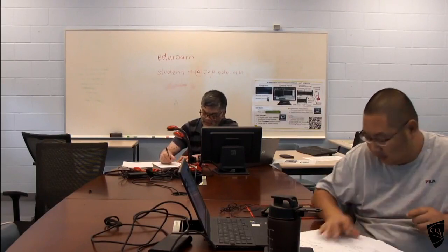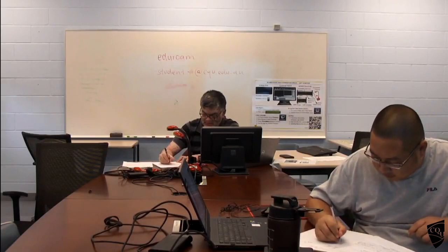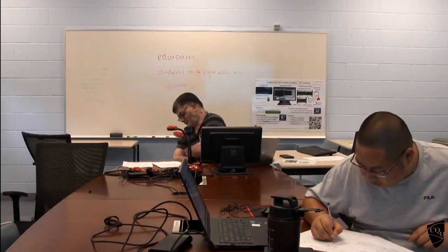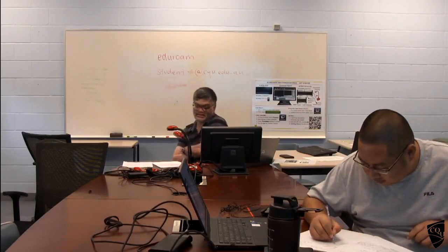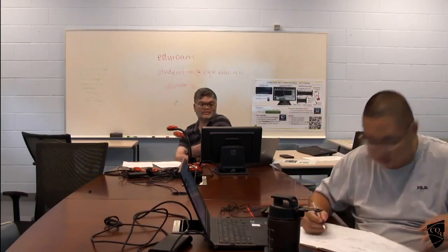So the distance is equal to y bar minus d by 2. So this is the I value for the rectangular section about the red line. What is the red line? That is the neutral axis which passes through the centroid of the whole section.